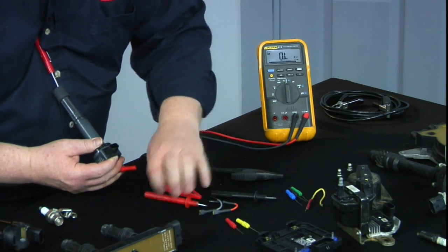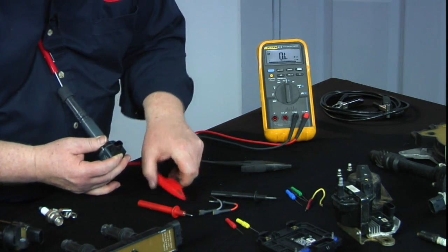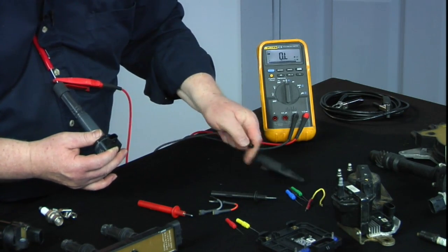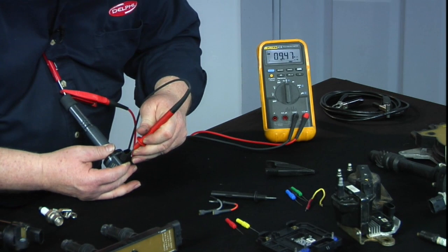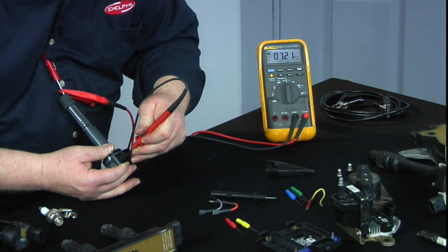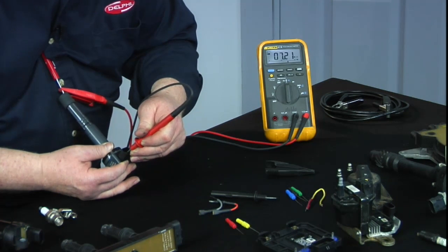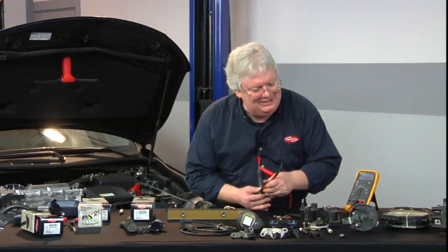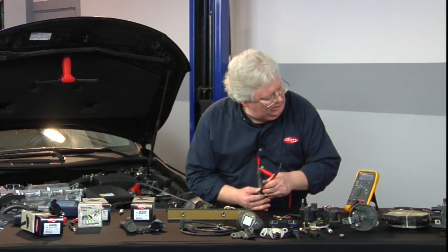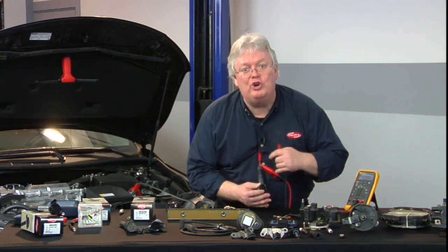Looking at the whole diode aspect, I'm just going to reverse the polarity here. Now with a reverse polarity, do we see any difference? We may or may not. We did, 7,000 ohms, 7 mega ohms. So those are some of the diodes the engineers were telling me about earlier when I called them today to find out, hey, what can I do and what can't I do on a 3 and 4 wire coil? And basically, I'm just seeing the presence of a blocking diode and the electronics internally, what's going on there.